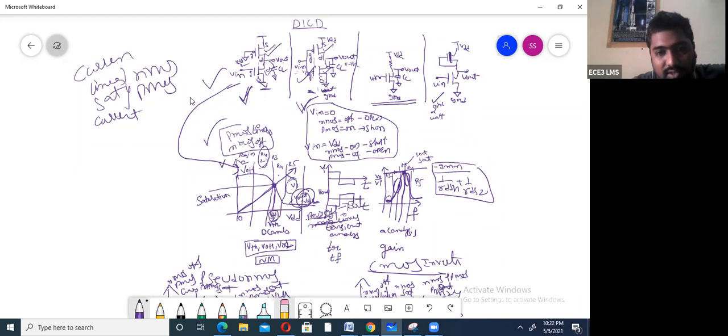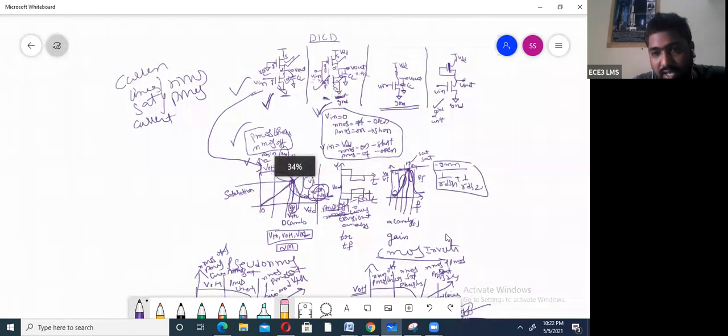And these two regions we are not finding. This is switching, in between switching, from VOH to the operating point to VOL. This is a switching point. Then the same for PMOS also. For any inverter you take, this is a DC analysis graph. Every DC analysis graph has 5 regions of operation. From this we are finding the noise margin. Then from transient analysis, mainly we are finding transient time and fall time.